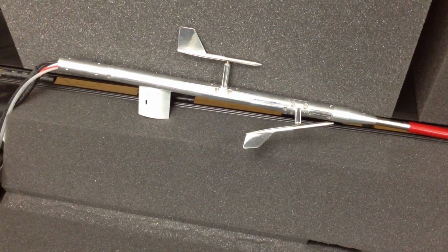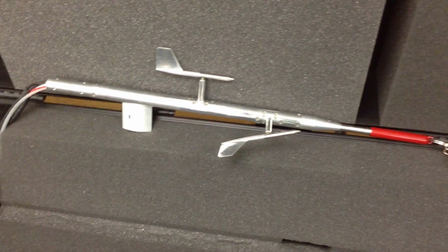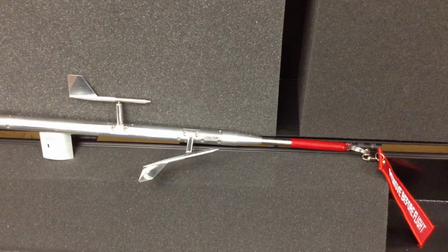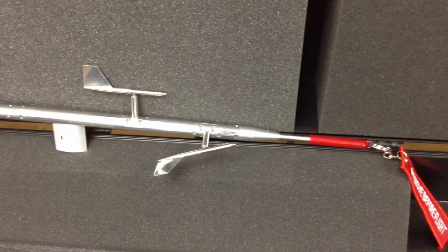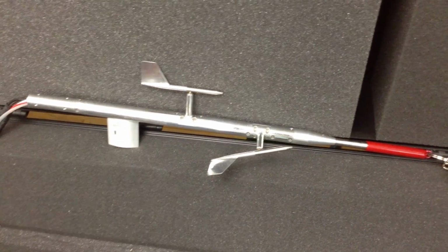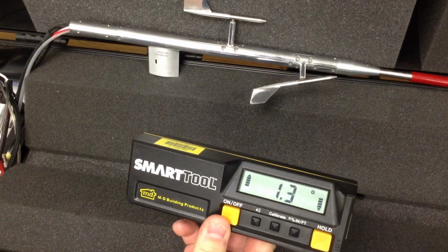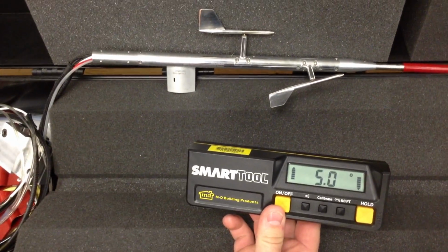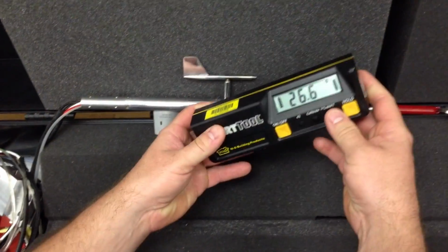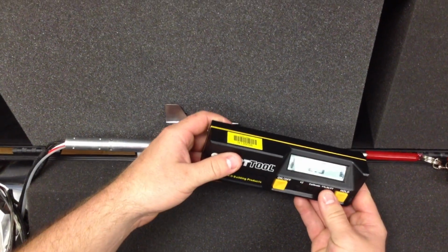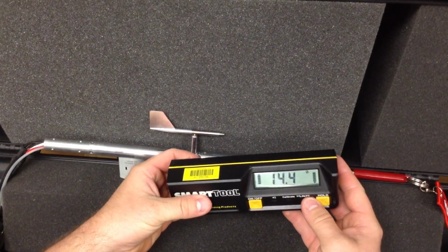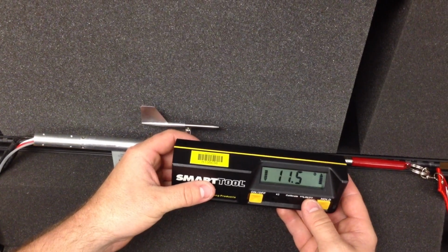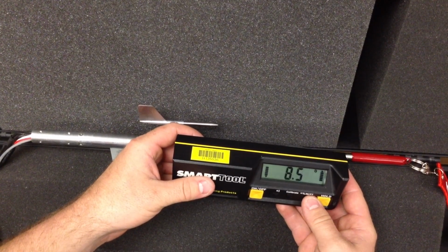In order to calibrate the alpha probe, we need to correlate the voltage being recorded through the DAC system to the probe angle of attack. To do this, we use a digital angle finder. The angle of attack and the potentiometer's output voltage are recorded in unison at multiple angles of attack. At least 3 data points are needed to properly correlate this data. However, 6 data points are recommended.